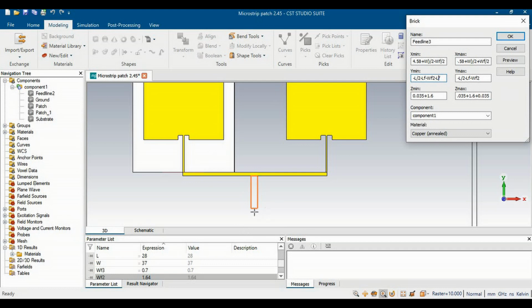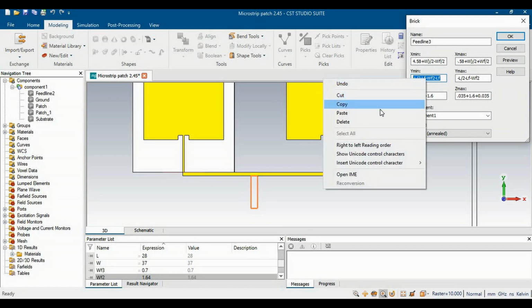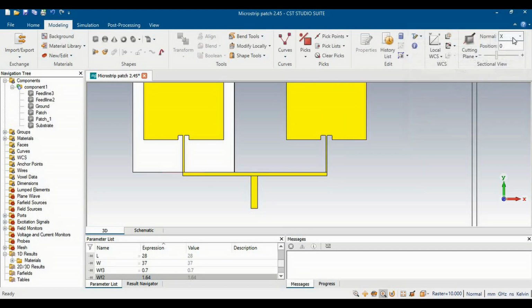So for defining the end point of the ground and substrate along the y min or the negative y axis, we can just copy the value of y min from here, right? Just copy the value of y min from this point, because we have to touch the bottom of the ground and substrate with this point, right? So instead of again defining the value of all variables, I am going to just copy these values, and we will directly paste these values while increasing the ground and substrate along the y axis, right?